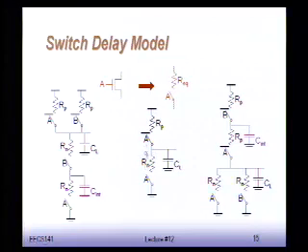This is an inverter, so there's only one P and one N. The one to the right is a NOR, right? There's 2 N in parallel and 2 P in series.